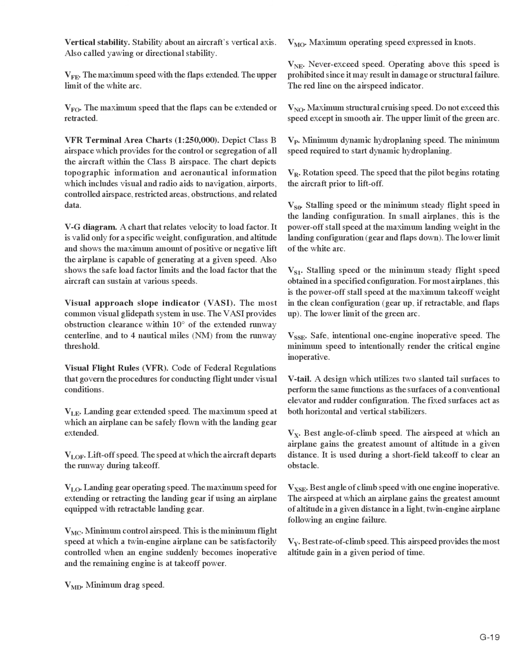VLO. Landing gear operating speed. The maximum speed for extending or retracting the landing gear if using an airplane equipped with retractable landing gear. VXSE. Best angle of climb speed with one engine inoperative. The airspeed at which an airplane gains the greatest amount of altitude in a given distance in a light, twin-engine airplane following an engine failure.